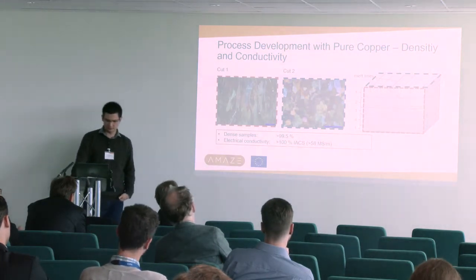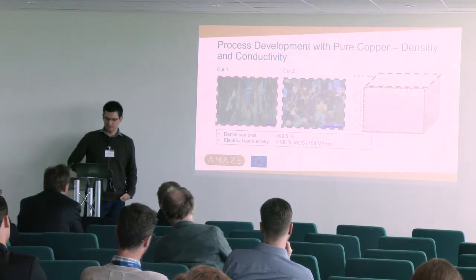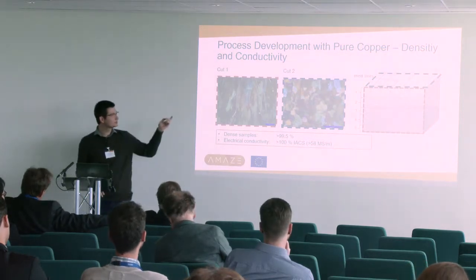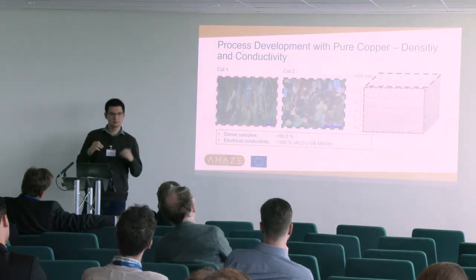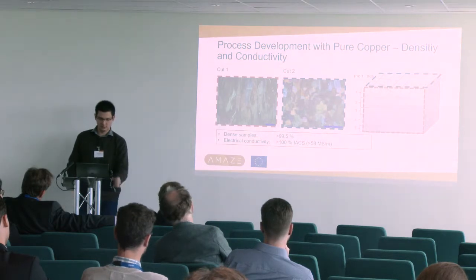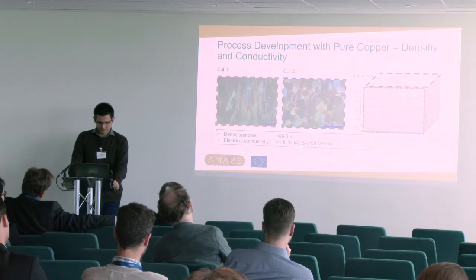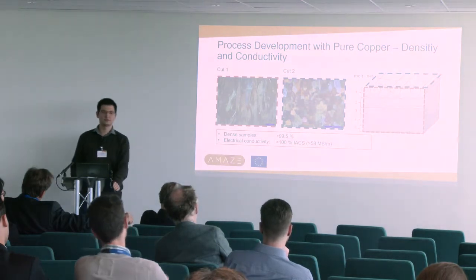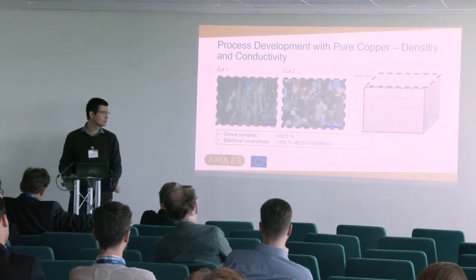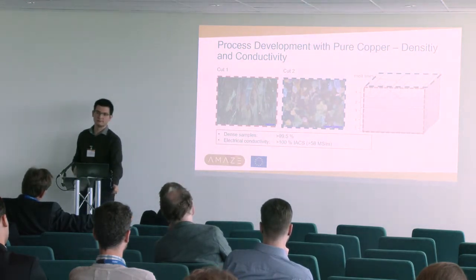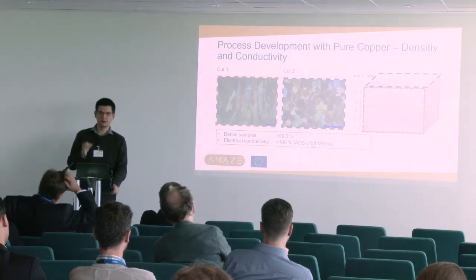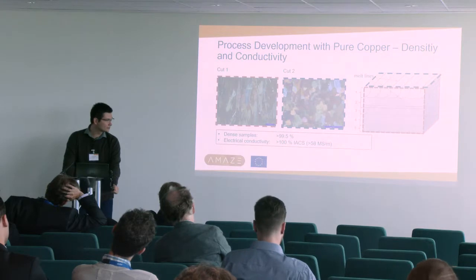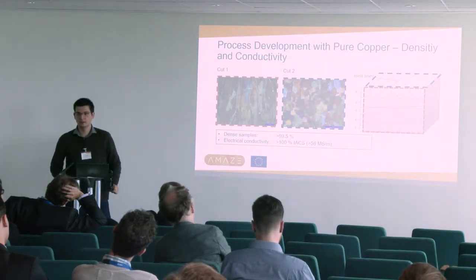The microstructure is pretty common to additive manufactured parts. Within the build direction, we get a columnar microstructure, and perpendicular to the build direction, which is the second cut, we get a somewhat equiaxed microstructure. So basically, we have columnar growth. We managed to produce dense samples with a relative density of 99.5%. So we have no binding faults and everything. These are really, really dense samples. The porosity left here is due to powder production, so the porosity in the powder, but not due to the process. And we also reach 100% of the electrical conductivity measured by eddy current.